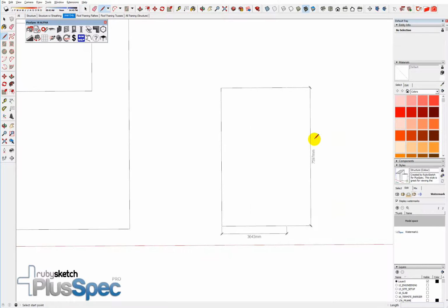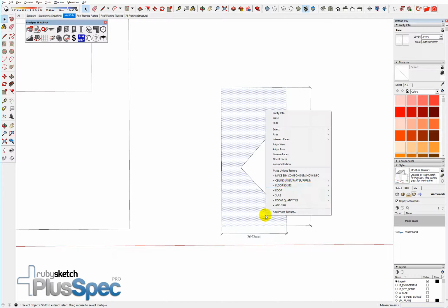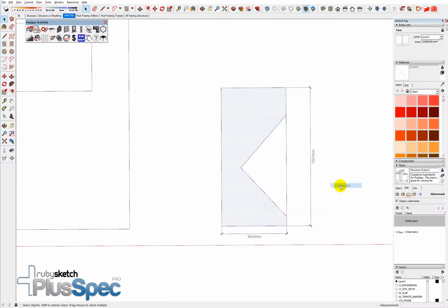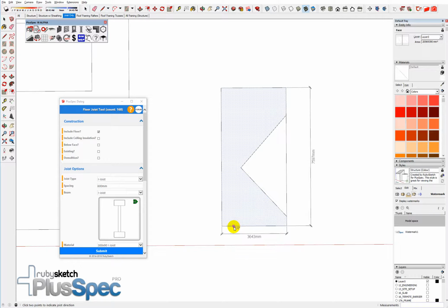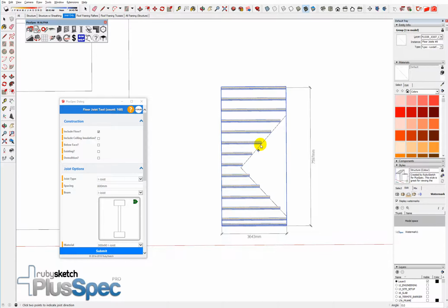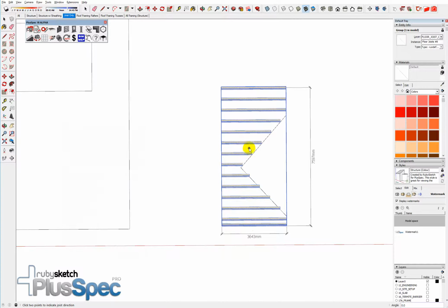So for instance, a lot of waste gets thrown in the bin because it's easier for a manufacturer just to send out all the same size joists. I just deleted the wrong line here. But what happens when we have something like this? Right, joists, create joists, tell them which way I want them to go. Okay, now we have a whole heap of different size joists. This is not as easy to estimate, especially because we have to purchase joists in cut size lengths.